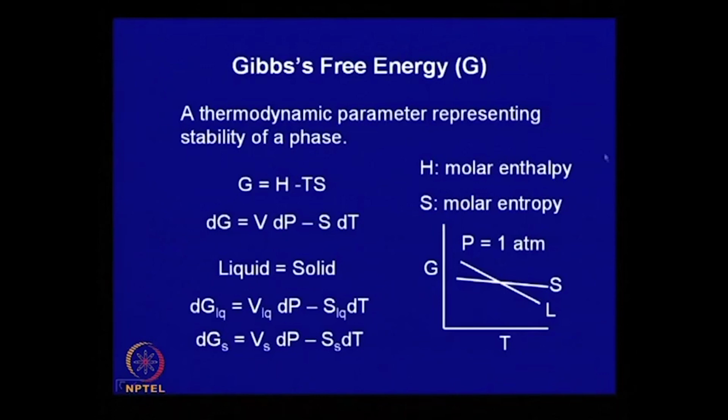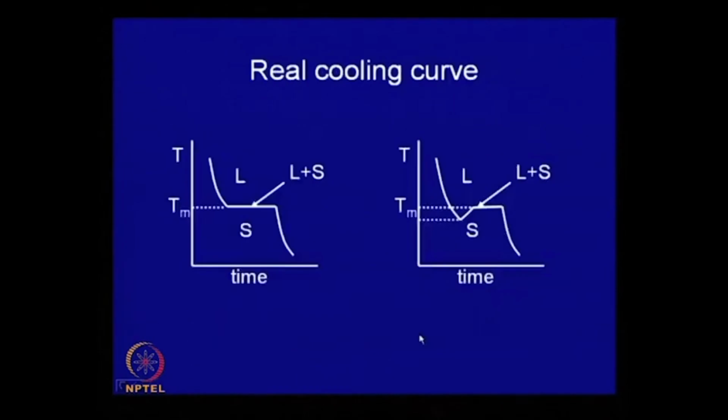So, that means energy has to be supplied, and this can come from this chemical potential, and this is possible only if you undercool a bit, you cool the system to a little lower temperature, then the solid has less free energy than the liquid. So, there is a net available energy, which is used up in creating new surface. So, for the solidification to proceed, you need some amount of undercooling, and this is shown over